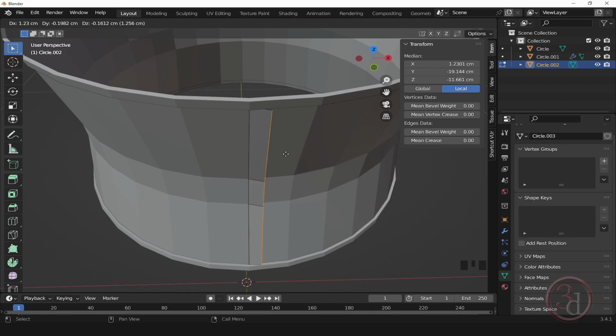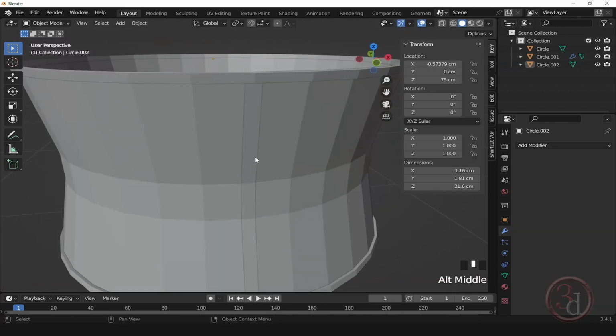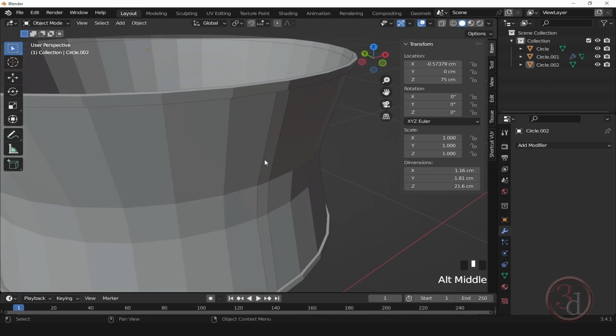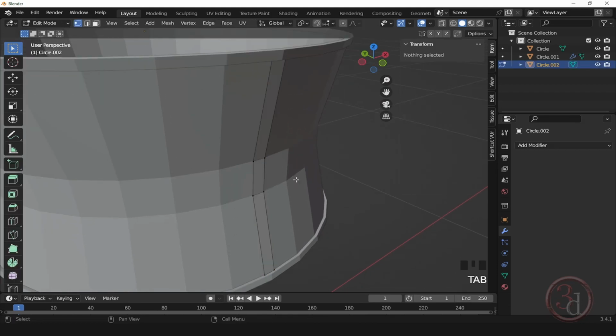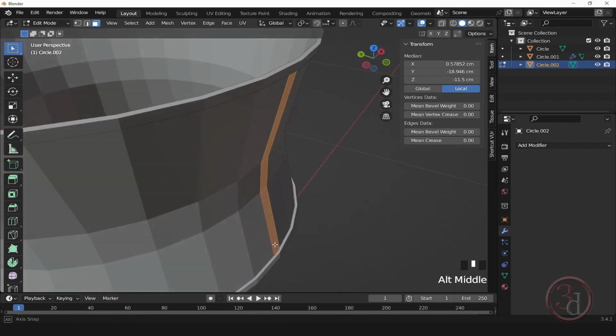And I will press the X key. And this much about here. All right, and now I will add thickness to it. So I'll select this, press Tab, and I'll switch to the face selection and select everything. Press A to select everything and then extrude it out.